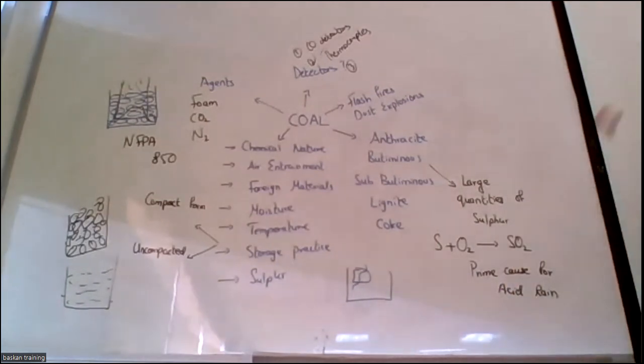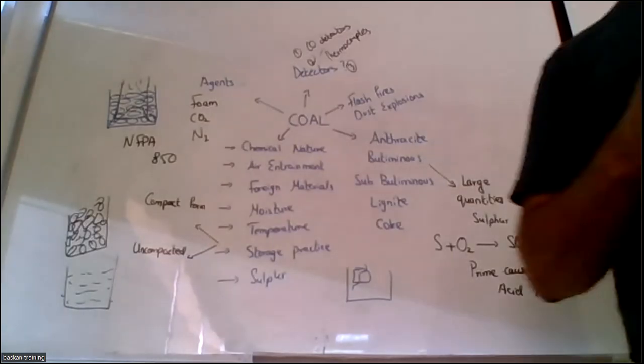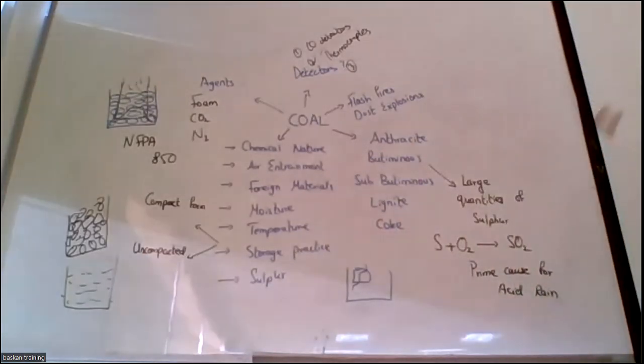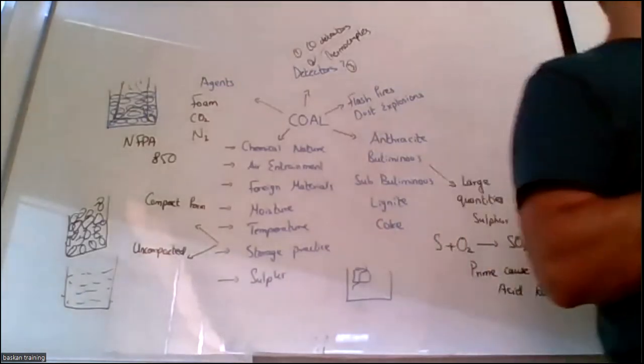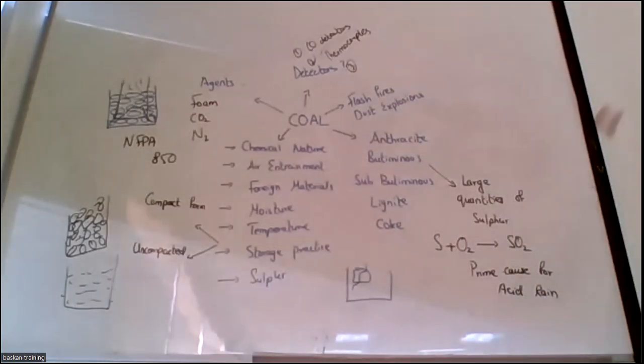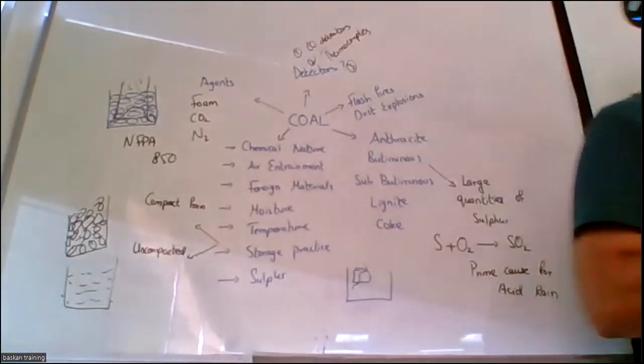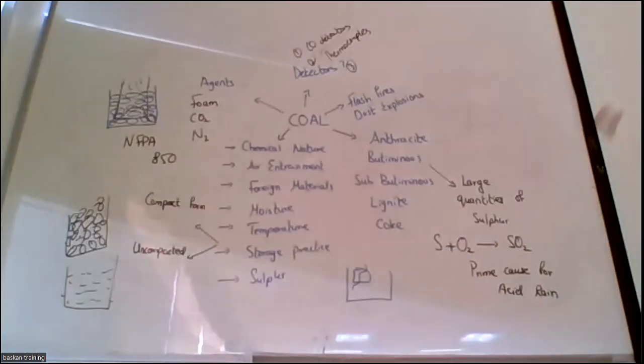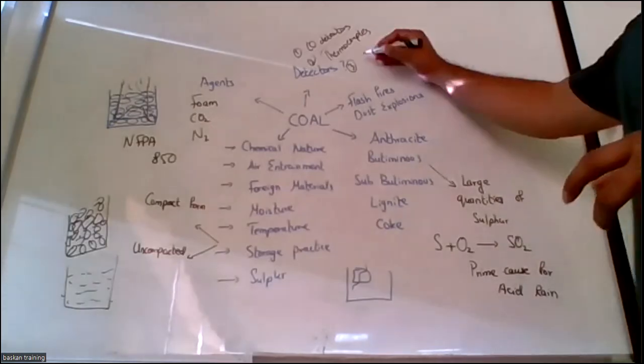Toxic gases, gas detectors, right? Which type of gas detectors? We discussed 3 types, right? Semiconductor, we discussed the catalytic element, and the third one was the infrared absorption principle. Infrared passes freely through diatomic symmetrical particles like oxygen and nitrogen. As soon as any asymmetrical particle enters, infrared is going to get absorbed. So infrared detection is used widely for toxic gases. So, infrared monitoring.